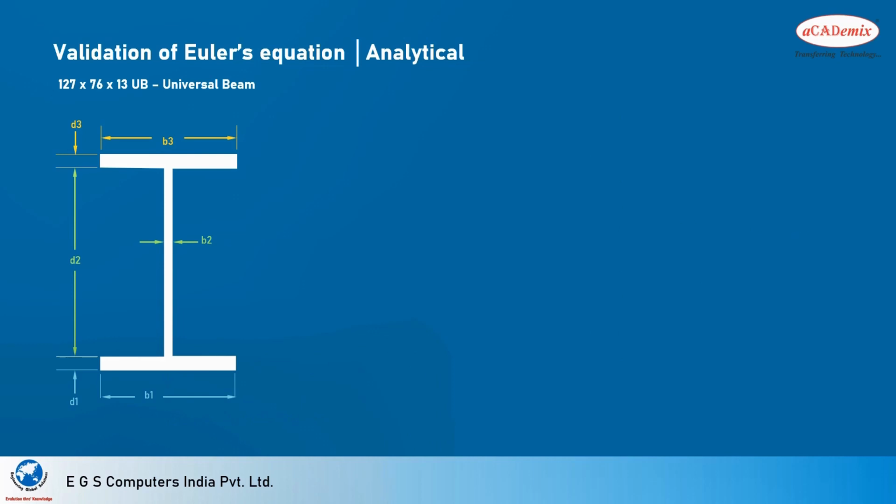Now we have the values of area moment of inertia in the xx direction and yy direction. We have already mentioned that the design calculation should be based on the smallest moment of inertia value. Therefore, the value that should be used for the buckling calculation is Iyy.